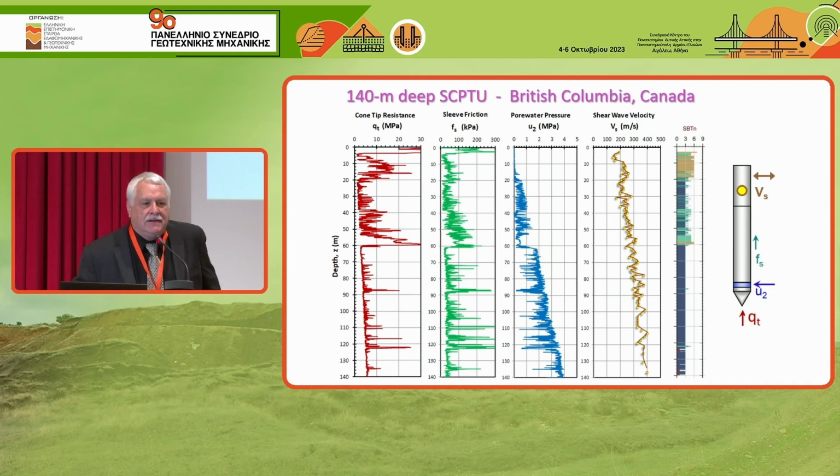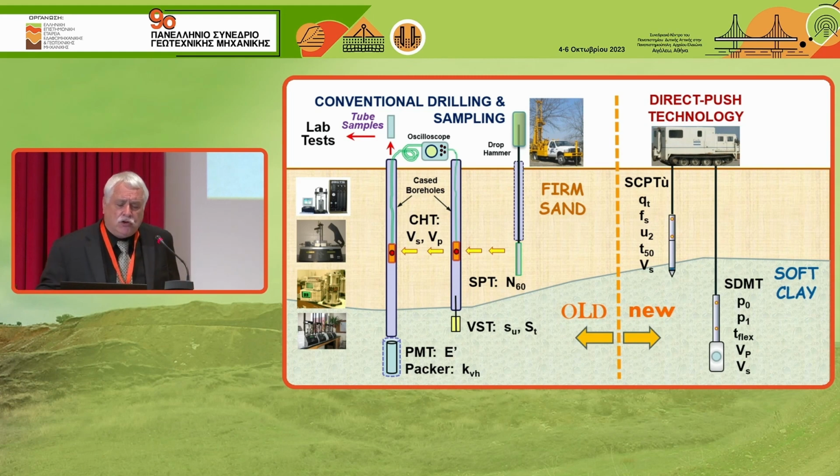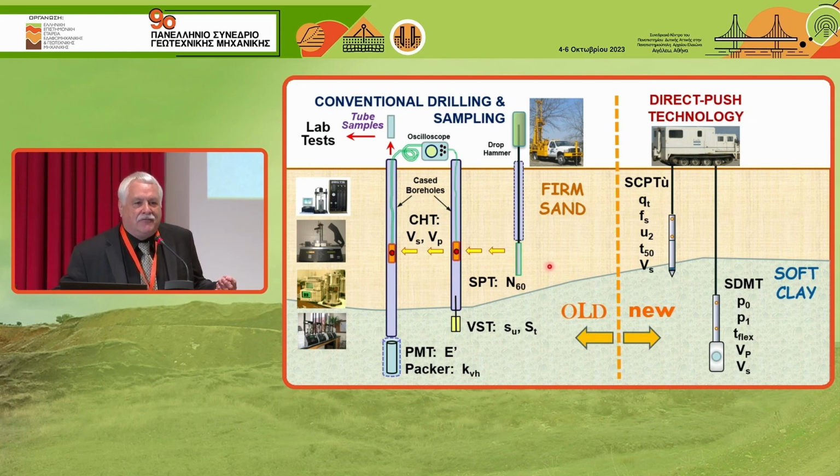If you can go deep. It's obviously geologic dependent. So we could do it the old-fashioned way. It's great. And I've had the pleasure of working on some large projects where I had literally unlimited money to go out and do soil borings, take samples, do cross-hole tests, standard penetration tests, vane shear tests in the clay, pressure meter testing to get modulus, packer tests to get permeability, all the lab tests I wanted. These were big projects that took 3, 4, 5 years, and I had literally several $1 million to do it. That's the conventional way. It's great.